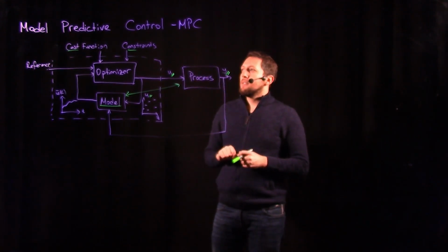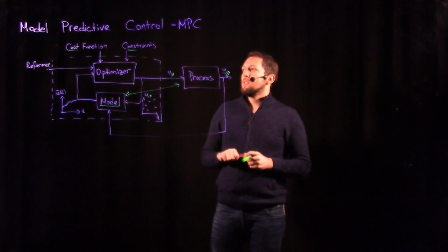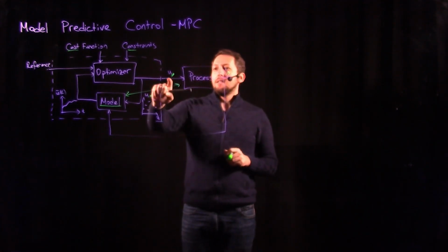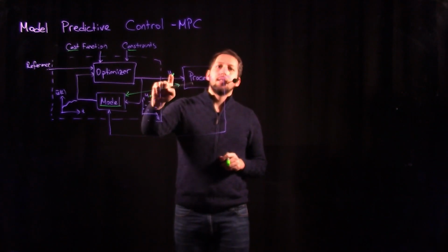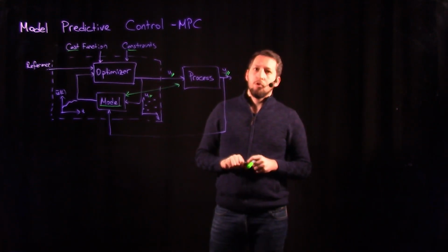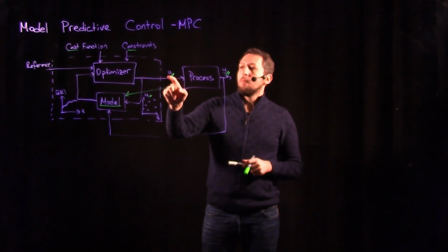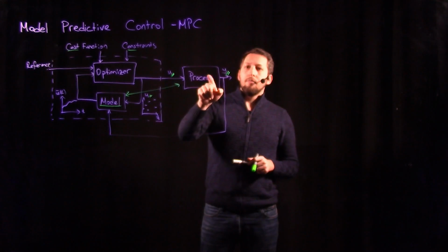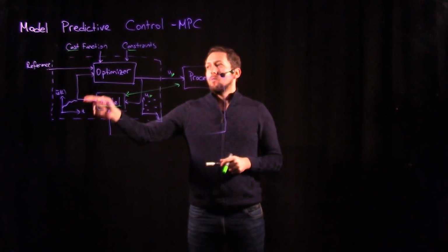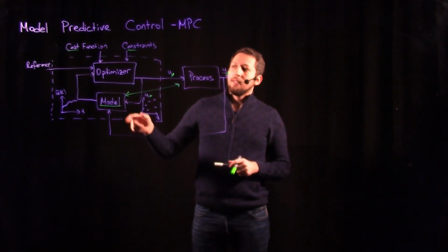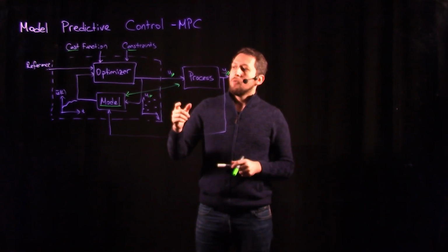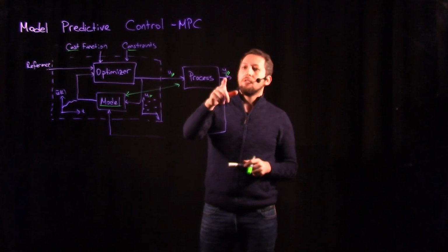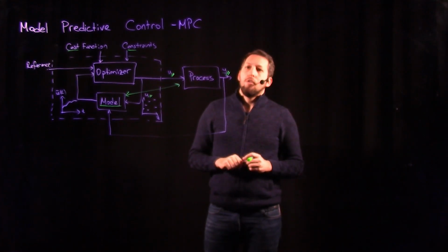One of the main things that we need to consider within the scope of model predictive control is that we need to create this control sequence at every sampling time, because we apply this control at the current time, and then when one time stamp has passed, we need to repeat everything from the very beginning, considering the new outputs of our system.